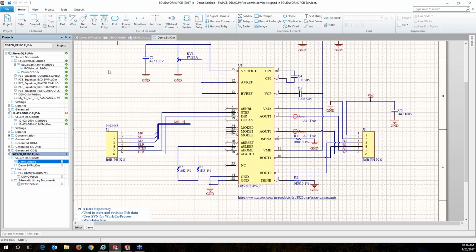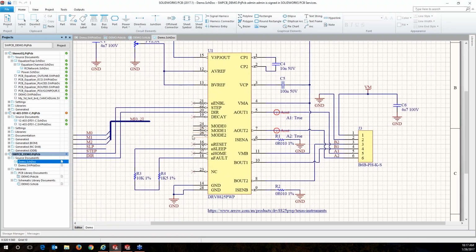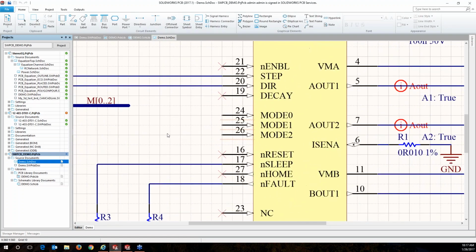So now let's zoom in a little bit and do some schematic work here. Let's say you want to work on this bus and you haven't quite done anything yet. You can go ahead and grab it and move it, just like you would expect in a schematic capture tool. You can grab some bus entry points, hit the space bar, and add all those type functions. Now bring it over, attach it to the pins, bring it back, and there are your lines all hooked up for you.